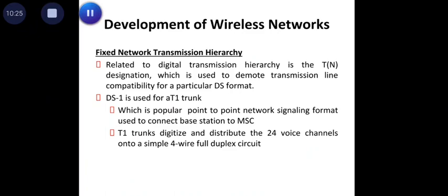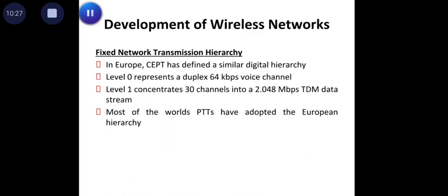4-wire full duplex circuit. In Europe, CEPT has defined a similar digital hierarchy. Level 0 represents a duplex 64 kilobits per second voice channel, and level 1 concentrates 30 channels into a 2.048 megabits per second TDM data stream. Most of the world's PTTs have adopted the European hierarchy.